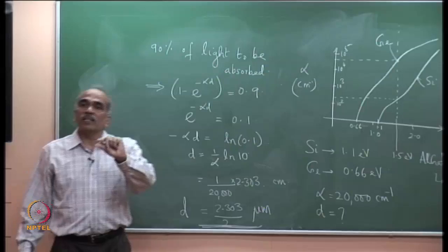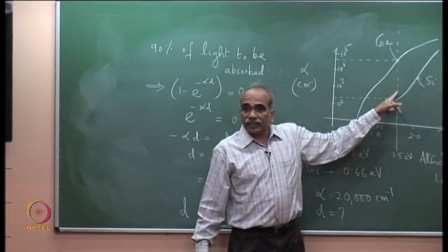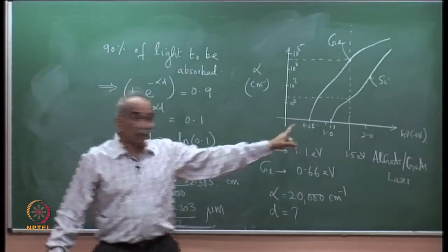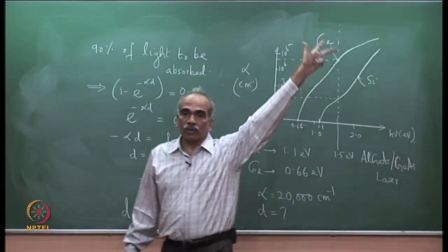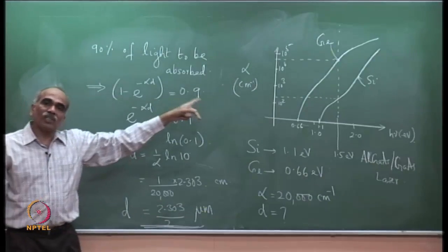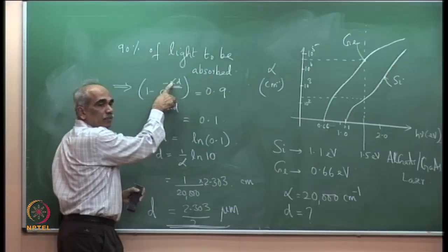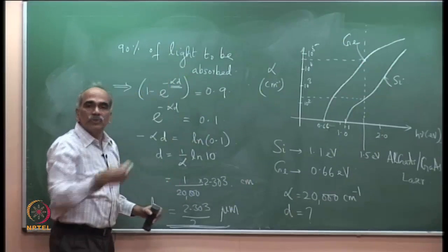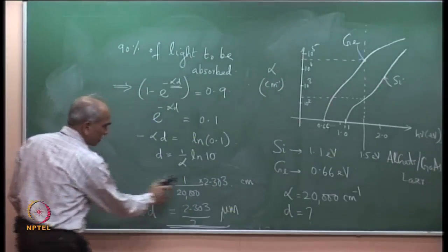So, if you take appropriate thickness, but if you had taken silicon as the detector at this wavelength, you would have required a thicker material at this wavelength, but somewhere later you will see that silicon will be highly absorbing at a later value of h nu. So, depending on the material you have to choose. The point is, choose the right material and right thickness so that this goes down to 0. Our objective is to maximize eta. All right.